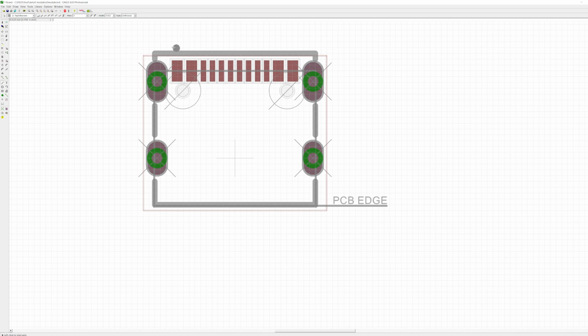And I'm also not going to copy the pin 1 notation here, because you can't rotate the thing. It's only going to have one orientation because it's a surface mount device and it's not rotationally symmetric. So I'm not going to bother with that. So now I just have to do the stop mask and the copper pads and the vias and the drills.